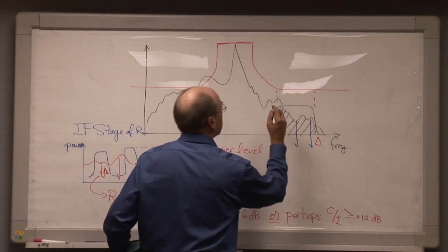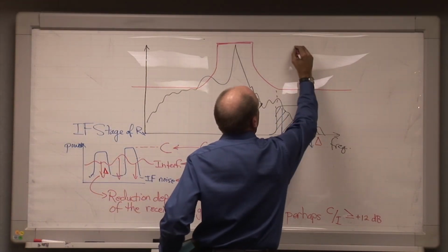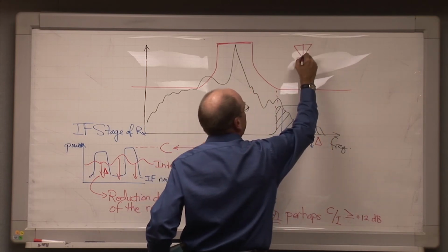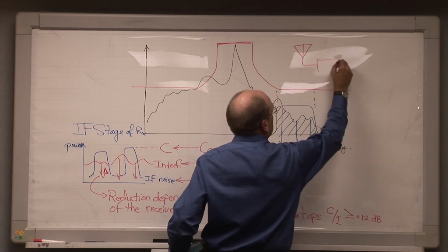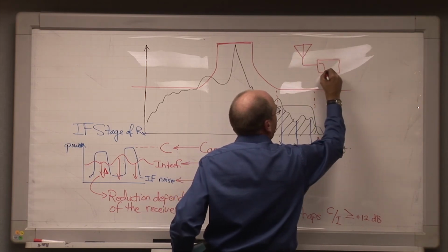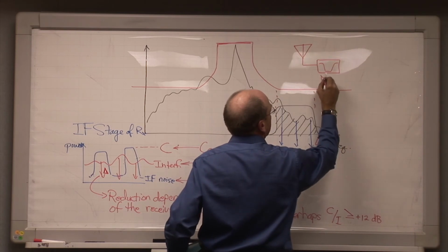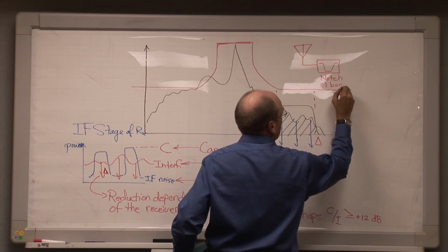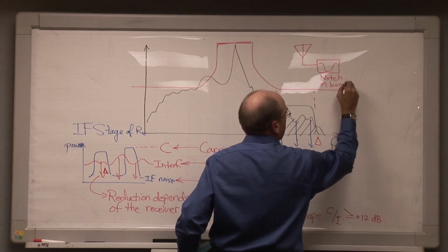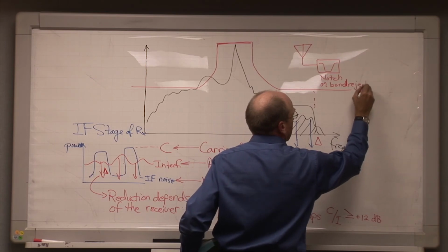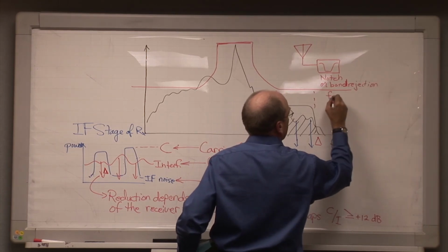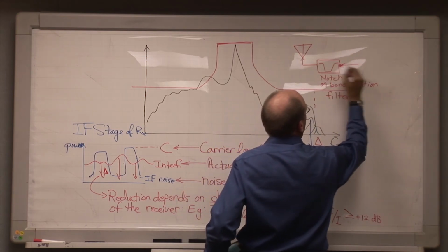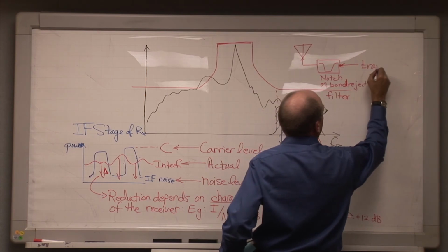So now what we can do on this transmitter is install, just before its antenna, probably at the RF, some kind of a notch or a band reject filter, or band stop, I'll say band reject filter here, where this is the rest of the transmitter circuitry.